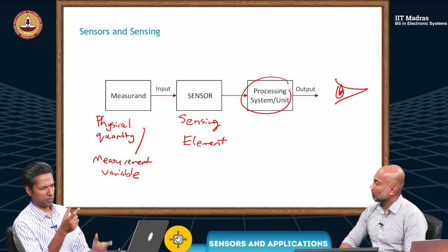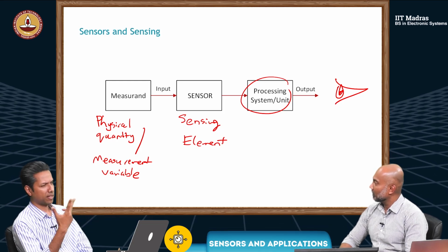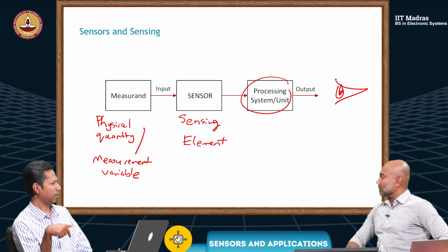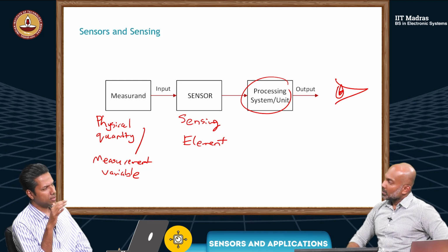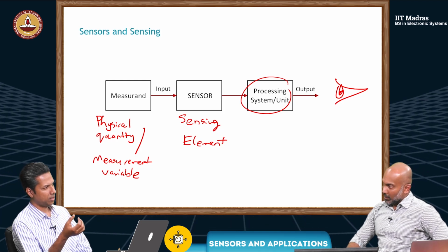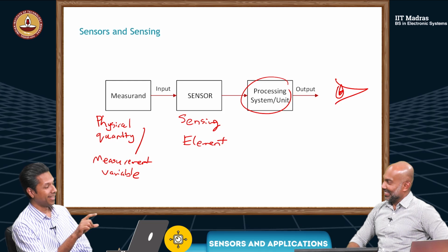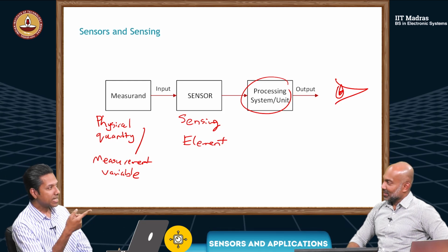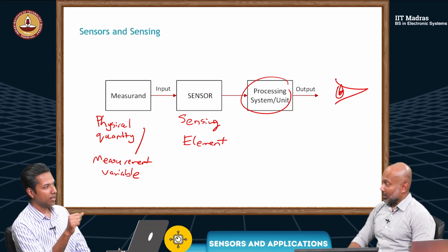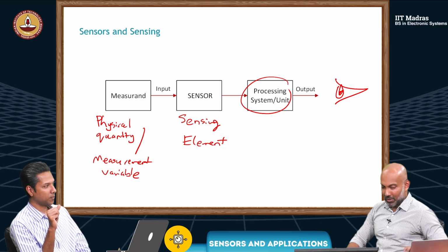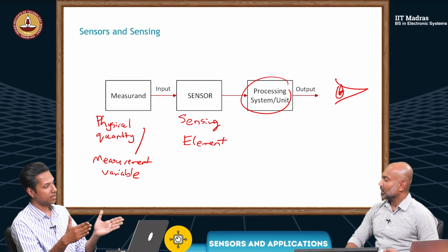See, I know, for example, if you take a resistor, the resistance of a piece of rod, conductive material, it's rho L by A. Rho is this conductivity. Mm-hmm. So when we change the temperature, I think this rho is the resistivity. Resistivity, yeah, not conductivity. So the rho changes with respect to temperature, correct? Yeah. There will also be some dimensional change. So L and A also may change. Yes. But effectively, there will be a change in resistance with respect to temperature.